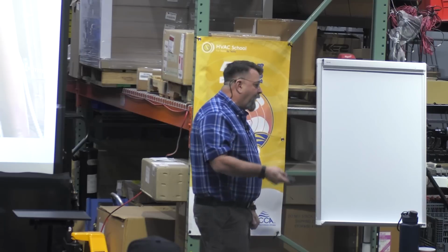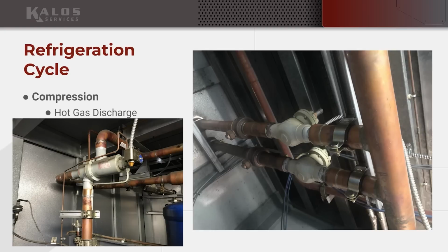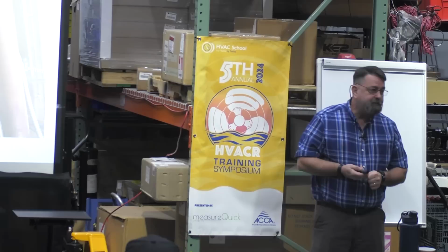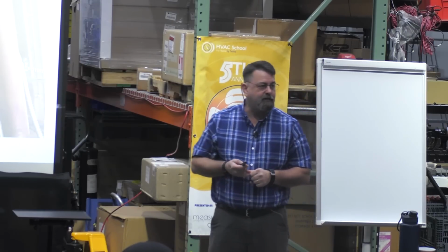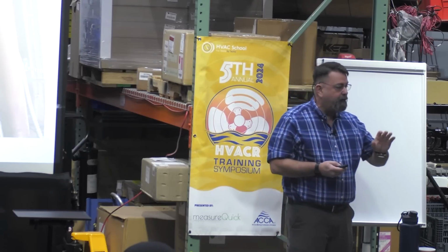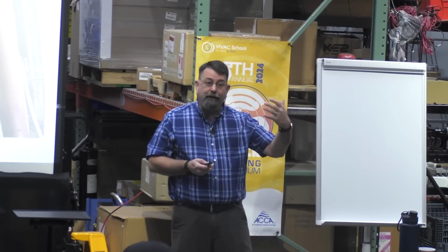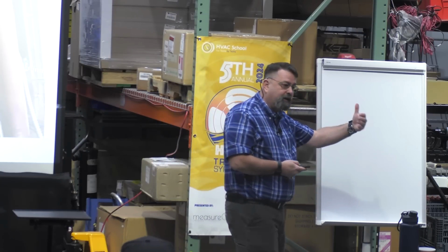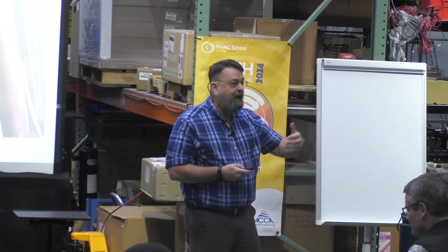Some of the common things that we see, particularly down in Florida, we see a lot of water, right? Every grocery store's got to have hot water. Well, I can heat it with my rack, okay? Makes sense? Another thing that we'll see really just about everywhere is dehumidification. We've got that reheat coil inside a dehumid, right? Where's that heat coming from? We can use this to reheat that air.